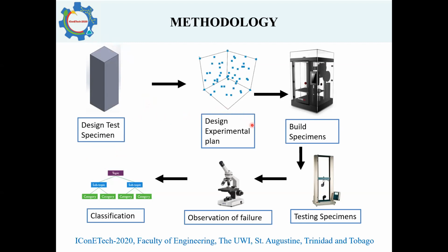In there, the build parameters are adjusted according to the design of experiments. The build files are then exported and printed on the 3D printer, and then packaged and stored in an airtight container with desiccant to avoid any moisture being absorbed into the plastic.